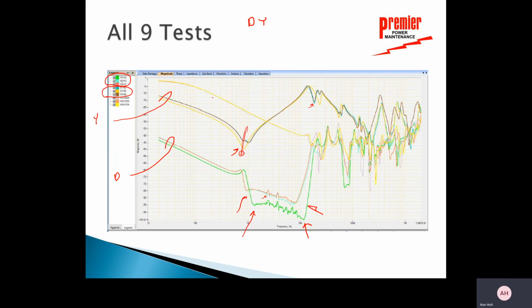And then finally, the third set of tests that we have here are the short circuit tests. So I'm going back and looking from the high side, but I've shorted the secondary windings out. And I can see some traces here. And I can't tell you right now everything that is happening over here, but I know that when I'm looking from 200 hertz up to about a kilohertz, what I'm looking for in that short circuit test is I want to see those lines right on top of each other.